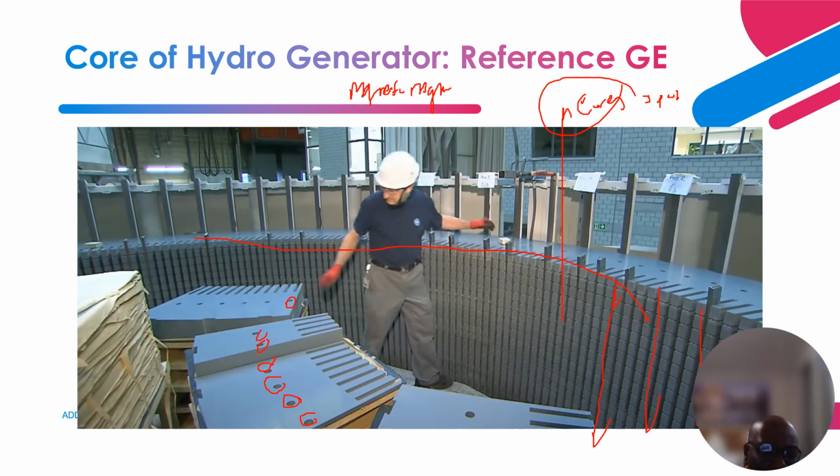Heavy, big bolts go through these, and the bolts are insulated, because remember, the goal is to prevent circulating currents due to eddy currents. So the bolting that keeps these laminations together has to be insulated.